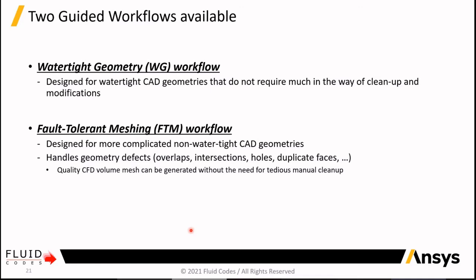In case the geometry is perfect, all the connections are fine, everything is clean, there are no holes, there are no leakages, everything is perfect. Just to give you an idea, it is exactly the same way you prepare the geometry when generating the mesh using Ansys Workbench meshing. So the geometry has to be perfect. We have the same approach here, but we can relax the conditions a little and take care of dirty geometries with a different workflow. Basically, we are wrapping the geometry with a surface mesh, and then we fill up the volume using this wrapping.